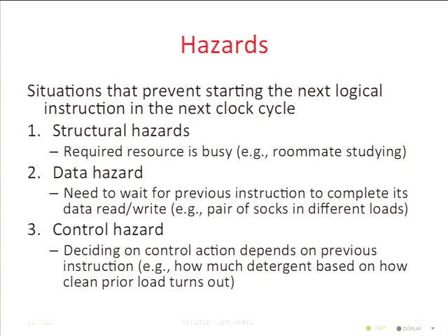You go back up to the top and go again, right? And only once do you actually go through to the bottom, okay? So if your normal guess is, I'm going to do this instruction, then this instruction, then the next instruction, most of the time for a loop, that's going to be wrong, because really what you end up doing is going back to the top. So that's another type of control hazard, okay?